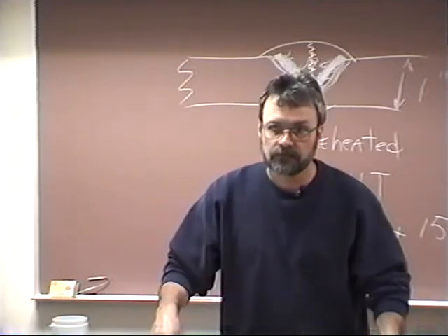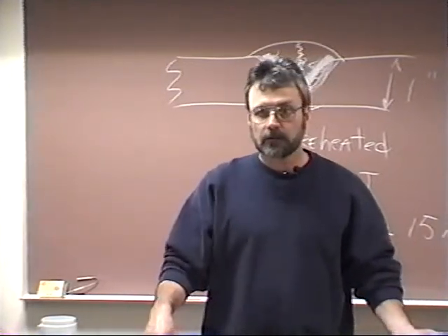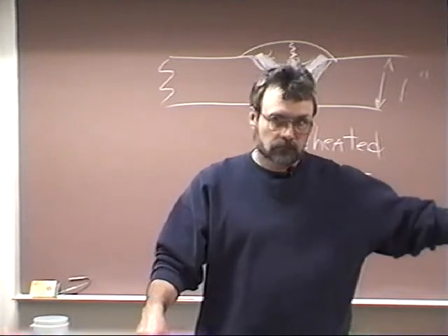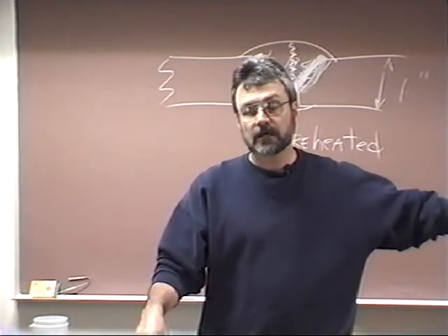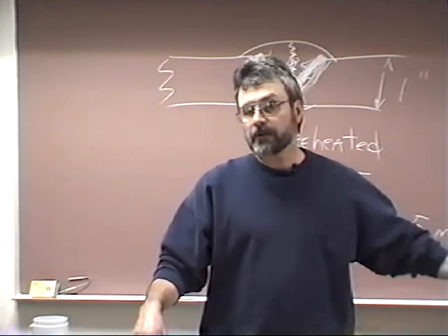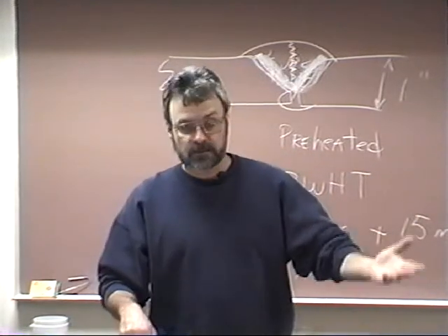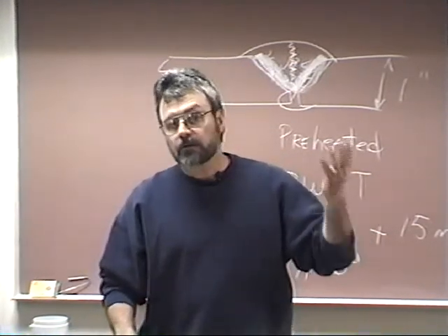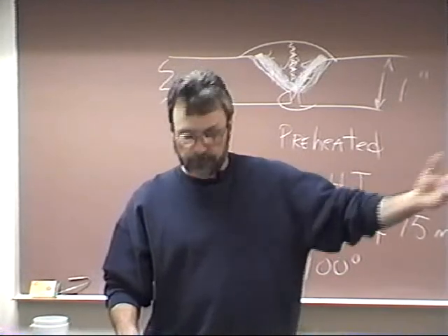First thing you're going to ask yourself is, is it within code? If it's within code, okay, it might be a discontinuity, but it's not necessarily a defect requiring repair. If it's outside of code, then it has to be fixed. And most codes require that you have a repair procedure to do that.